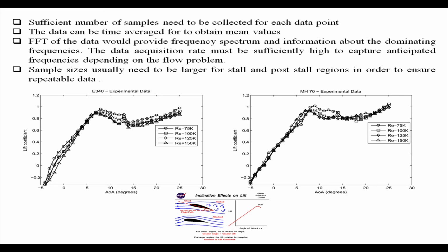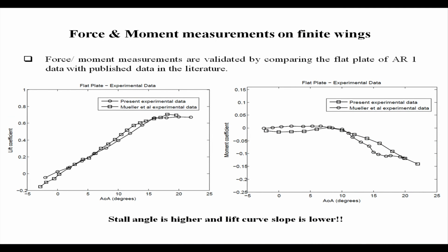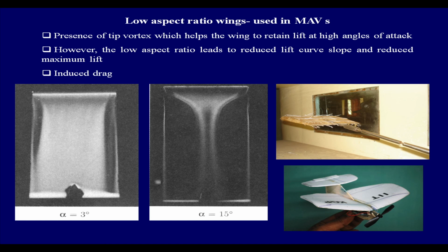We could strike better performance, yes, with the finite. Previous slide, sir. At alpha 15 degrees, the lift is decreasing because of that blanketing. The lift gets reduced. No, actually, what is happening is that I have a stable vortex here, somewhat similar to what you see in the delta wings. So, until that disintegrates, I am still going to have fairly good performance.